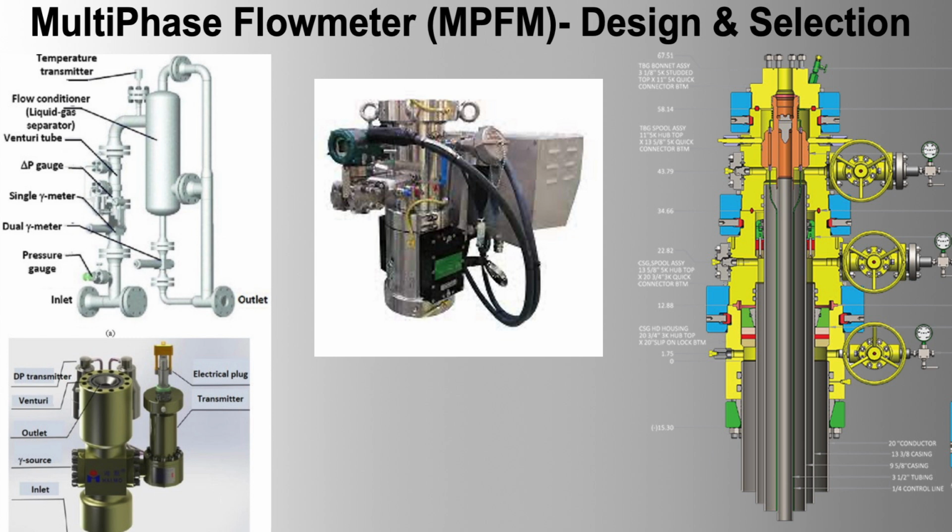4. Monitoring and control. Real-time adjustments. Continuous monitoring allows for real-time adjustments to chemical injection programs based on changing flow conditions. Feedback loop. Integration with DCS SCADA systems provides a feedback loop for automated control of chemical injection, improving responsiveness and reducing manual intervention.